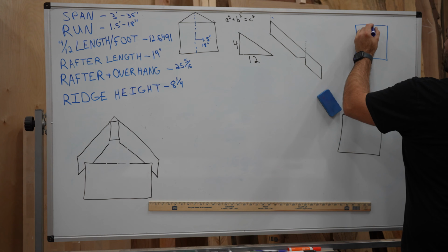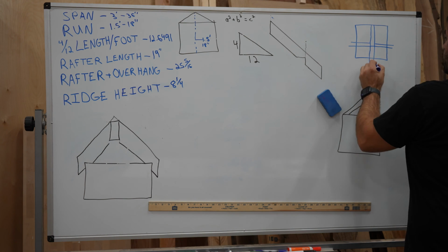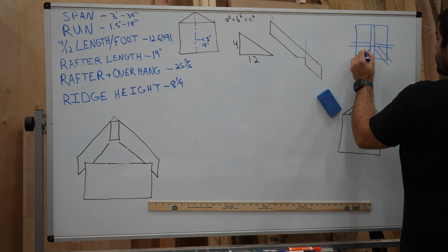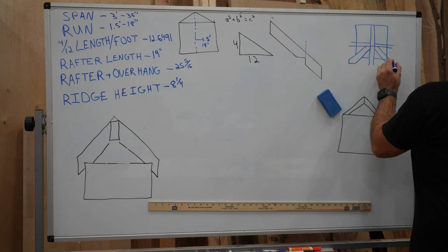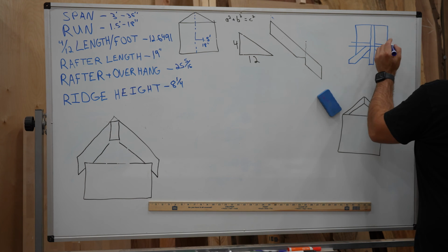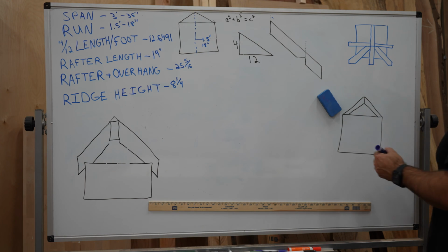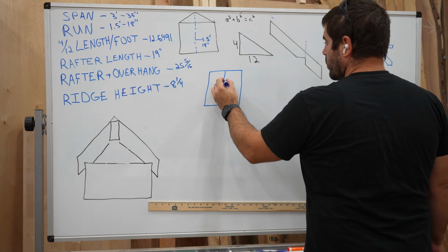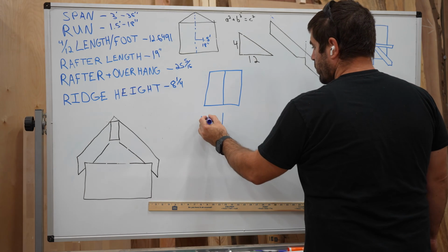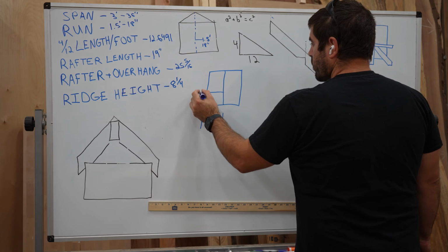So just like the last video, I want to go over where the numbers for the hip rafters come from. The first thing we need to do is find the length of the hip rafter. We will still be using our 3x3 model we used last time. So looking down from the top of the model, the hip goes at a 45-degree angle from the corner. For our first calculation, we need to find out what the horizontal distance is from the outside of the corner of our model to the inside corner where the hip meets the ridge board.